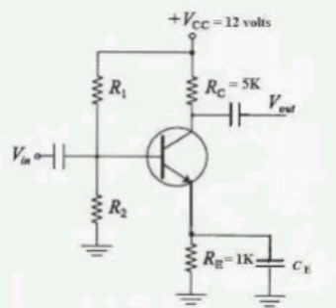Loop gain VO1 dash by VO1 equal to 1 plus SRC into minus 1 at numerator part, denominator part SRC into 1 plus SRC. That is nothing but loop gain equal to minus 1 by S square R square C square. Put S equal j omega. Loop gain equal to 1 by omega square R square C square. Put omega equal to omega naught. Loop gain equal to 1. That implies 1 by omega naught square R square C square equal to 1.